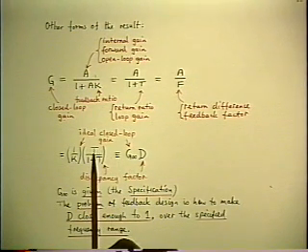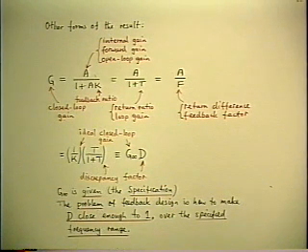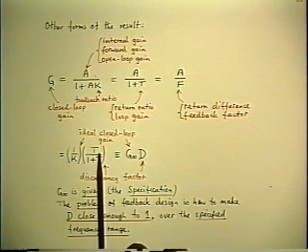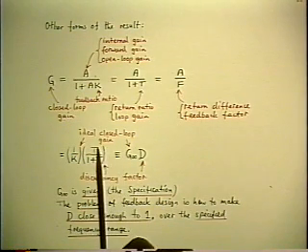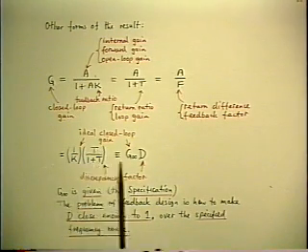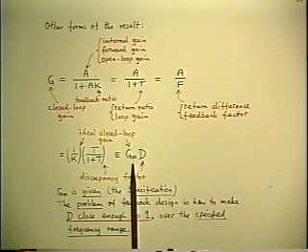So it's a reasonable expectation that if feedback is going to be any use at all, the more you have of it, the better. Which means infinite T is the ideal limit. And so if you could make an amplifier with infinite T, its closed loop gain would approach 1 over K.